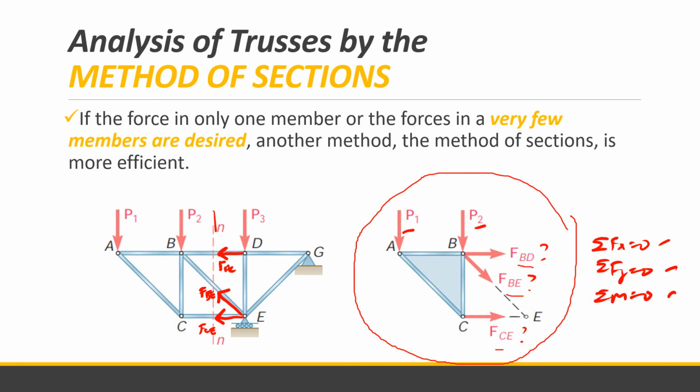You can also use this side of the truss, where you have the reaction EY, reaction EX, and reaction G. Using this member, you can find our unknowns. It depends on your preference. There are problems that are easier in one section compared to the remaining section. For example, this section is probably easier compared to the right section, because fewer forces are involved.